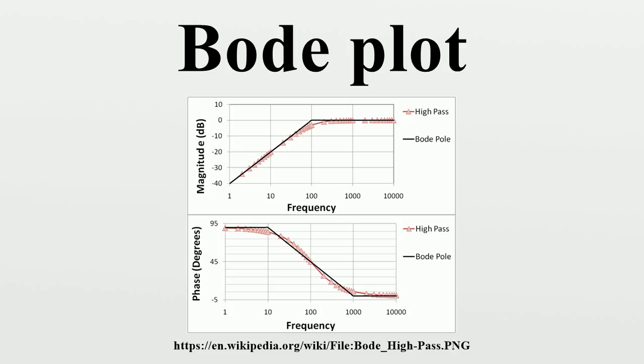Examples. High-pass filter. The one-pole high-pass RC filter has the transfer function, where the cutoff frequency is the inverse of the time constant. Magnitude plot. To obtain the Bode magnitude plot, one calculates the magnitude of the transfer function along the imaginary axis. The last equality is obtained using the rules for complex numbers. On the Bode magnitude plot, decibels are used, and the plotted magnitude is in decibels.